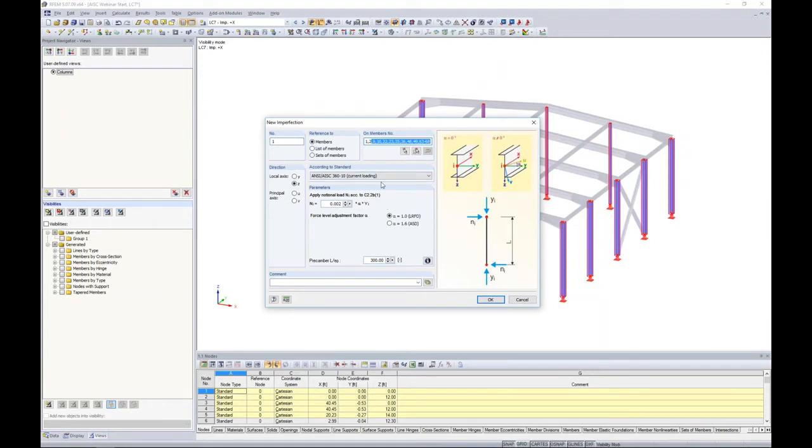And this should look pretty familiar because in this drop-down, I've selected AISC 360, 2010, current loading. Well, this is the equation for notional loads. We even give you the code reference according to C2.2b. Here's my 0.002 factor. We do allow you to modify that if you choose to do so. We have our alpha factor according to LRFD or ASD. And then our Yi. Yi is going to be those gravity loads, our dead load and live load, applied in our structure.